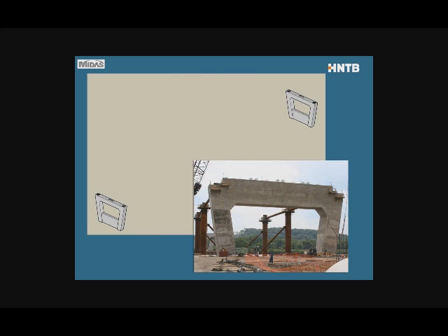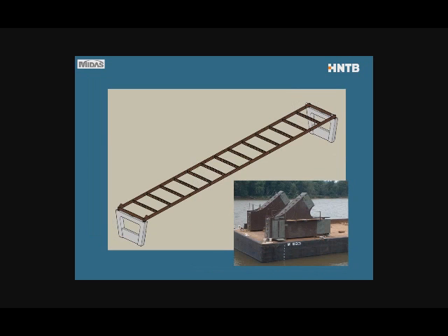And on top of the piers, unfortunately my pointer doesn't seem to work with this. On top of the piers you can see the bearings, 4 bearings, 1 on each corner, and then those little things in the middle on top of the piers are the wind locks to take out lateral shear forces. In the next picture, I added the tie girders. So those are the longitudinal girders. Then we have the intermediate floor beams, and then in the corners are the knuckle joints.